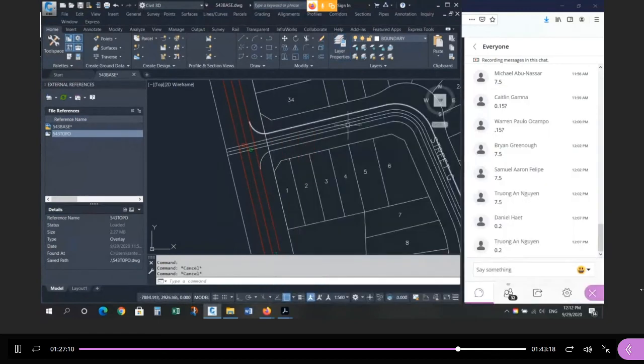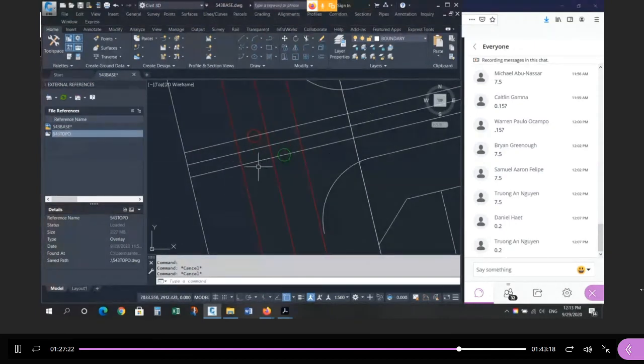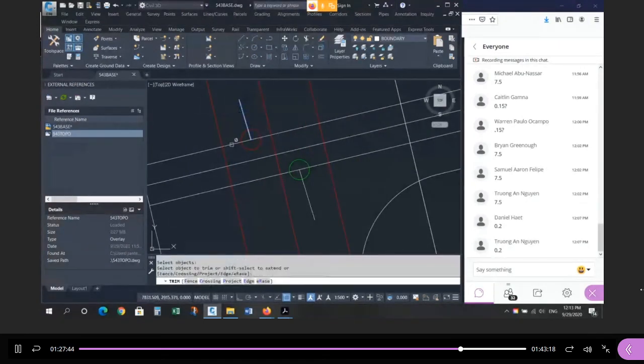When you zoom in here, you'll see at the intersection, this is from the topo now, remember the X reference? You'll see the sanitary is on one side and the storm is on the other, and you'll see they're approximately 1.5 meters either side of center. So you don't really have a choice in the subdivision. This has to be the storm sewer, this has to be the sanitary sewer. So once you determine 1.5 meters either side of center, go to the topographic information and see which you're connecting to. On this side, you're connecting to sanitary, on this side, you're connecting to storm, and that's where you cut it off.